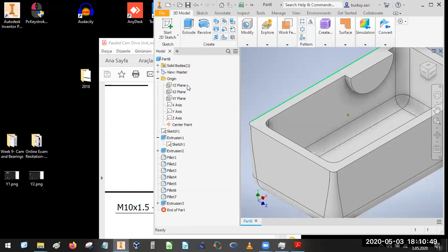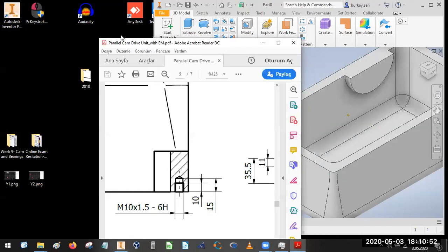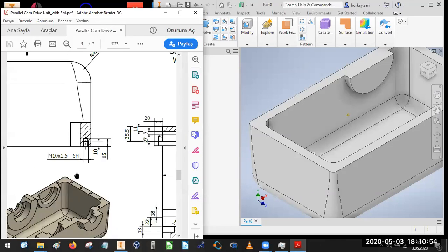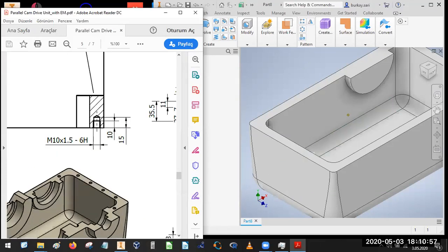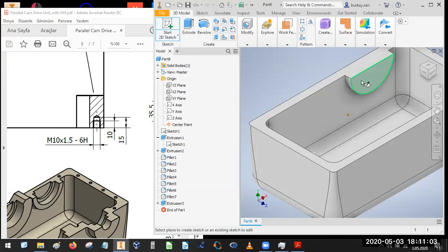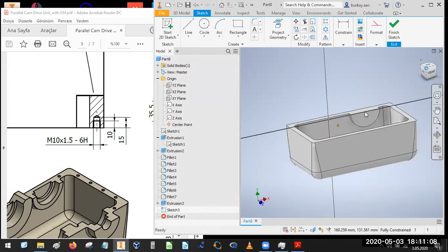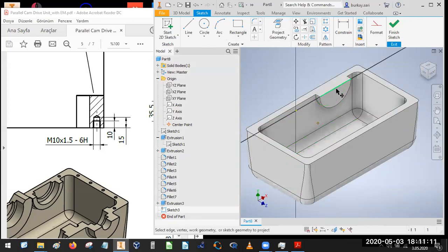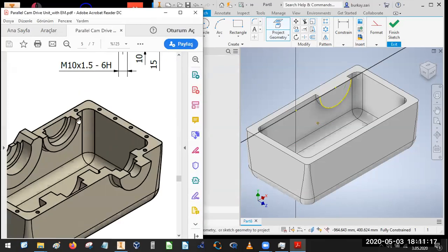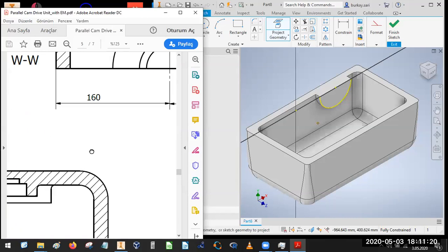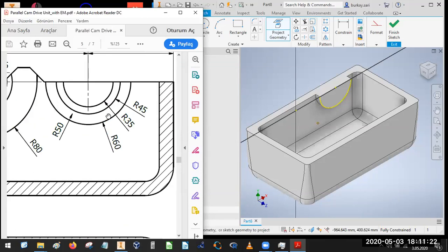The next thing I'm going to do is create the cuts one by one. Here, I have the outer diameter, and I would like to create a new sketch, but this time I need only the geometries that I have on the back side. I have the geometry for outside, but for this one, I need the geometry here. You can also create that geometry, which is the 45. We have a ring here left to 45.